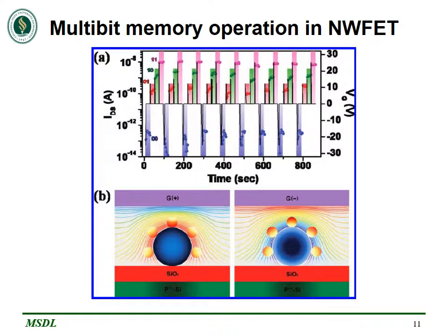Furthermore, more dense equipotential lines around the upper part of the nanowire easily induce more polarized charge at the ferroelectric and nanowire interface, resulting from a greater amount of reoriented electric dipole moment. Thus, different conductance states result from different net amounts of the applied electric field strength.